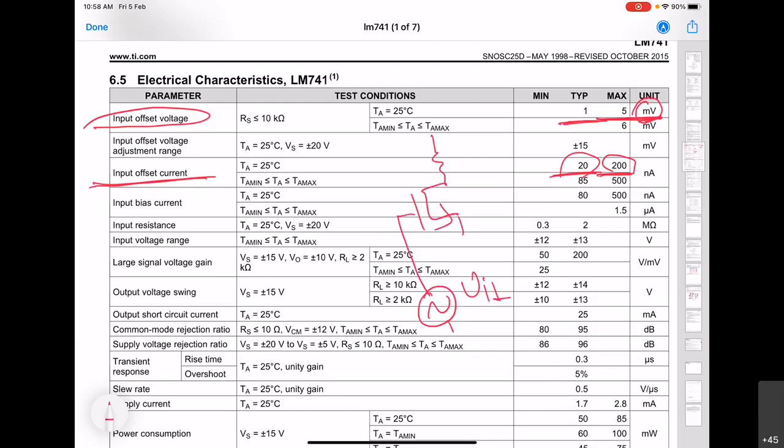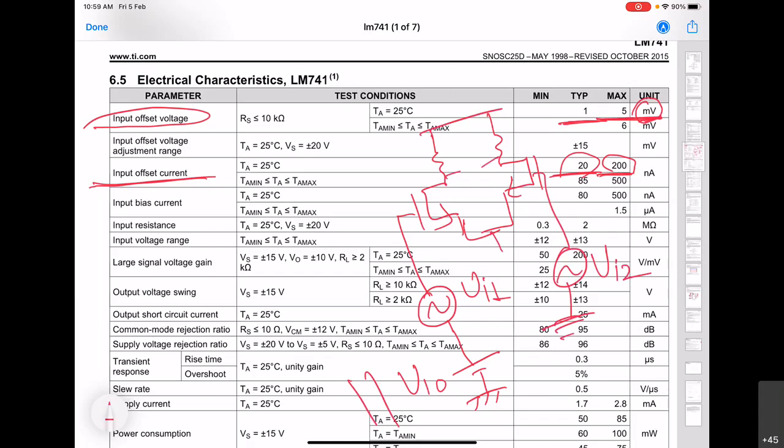In addition to that, there might be certain small DC that we will have to apply, say VIO, to one of the MOS to get no DC at the output. So this might be the scenario of using MOS in the incorrect way to get rid of the DC output that we get here.